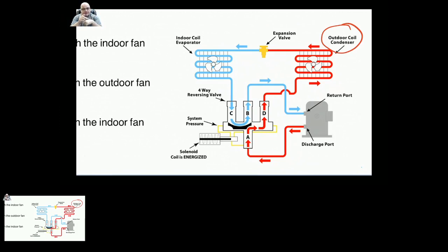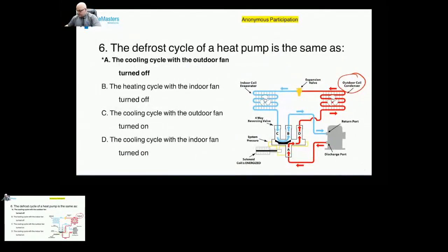But here's the thing. Remember, guys, any A coil you have installed in a furnace is exposed to temperatures that go from 40 degrees Fahrenheit to 140, sometimes 160 degrees Fahrenheit. You have those A coils built like that. So the manufacturers know how to build those coils, whether it is an evaporator or a condenser, doesn't matter. The fundamental structure is the same. They know how to build a coil in a way that the thermal contraction and expansion is not going to cause an extreme problem.